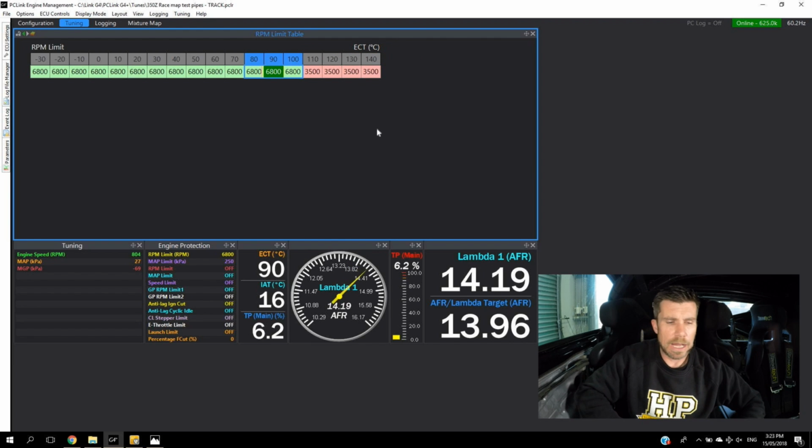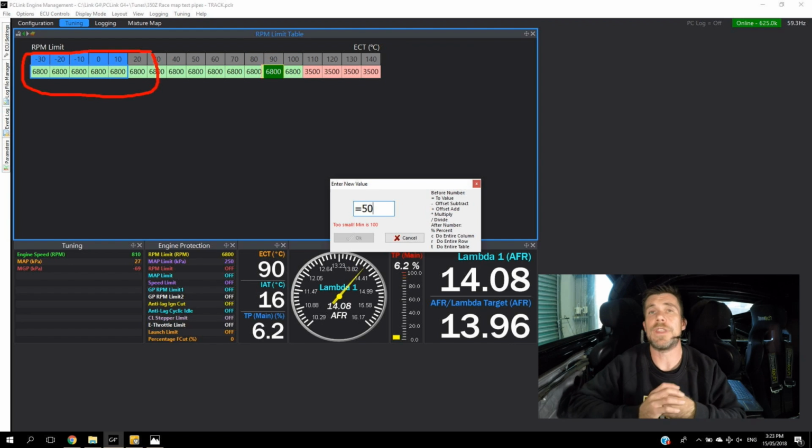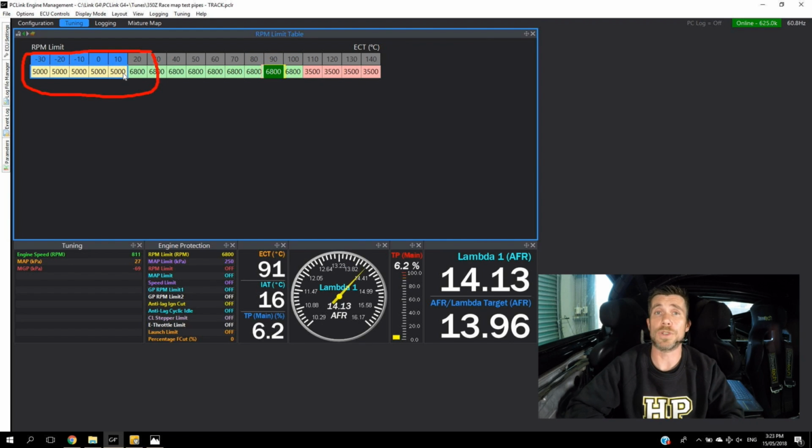save the engine. Likewise, another option we can instigate here is to also include a lower rev limit when the engine is very cold. This is something that I have used on a few of the engines that we built through my old shop, where we want to protect our reputation and make sure that the customer gets a good long life expectancy out of the engine that we've built.